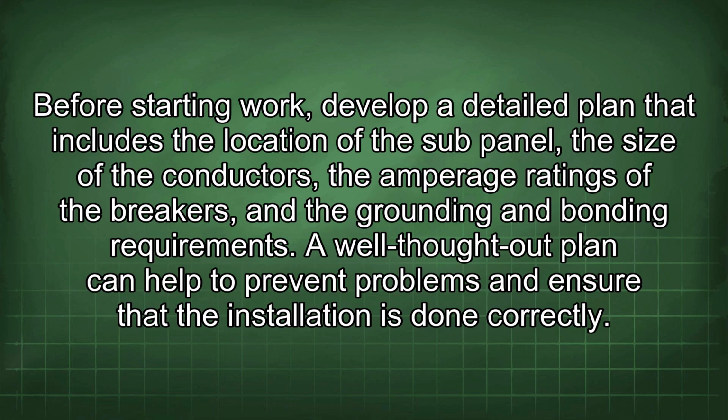Before starting work, develop a detailed plan that includes the location of the sub-panel, the size of the conductors, the amperage ratings of the breakers, and the grounding and bonding requirements. A well-thought-out plan can help to prevent problems and ensure that the installation is done correctly.